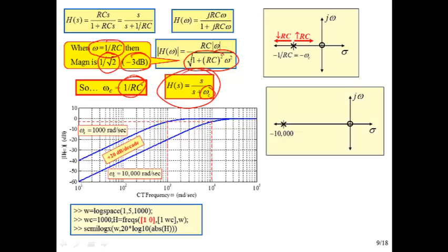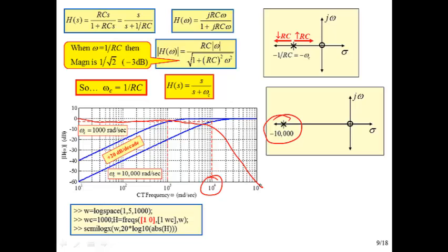So just like before, now I'm doing some MATLAB commands there, and because of the S in the numerator, I have to have a 1, 0 there to account for the fact that I have S plus 0 in the numerator. And so now what we're seeing here, as we have a pole all the way out here, that's pushing our cutoff frequency further out to the right, just like before, except now instead of coming across and dipping down, the cutoff frequency happens in the opposite way. We're coming up and then it levels out.